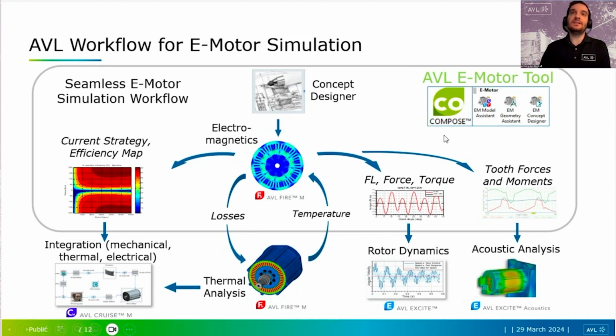And then with the results of this electromagnetic simulation, you can carry it over and start doing analyses in those three tools that I had mentioned earlier, CruiseM, FireM, and Excite. And these are the studies that I'm talking about where you want to understand your motor requirements and viability within a given application. That would be your system modeling. You want to understand your thermal behavior of the motor. That's your CFD FireM run. And then your rotor dynamics and acoustic analysis, and that's your Excite analysis.